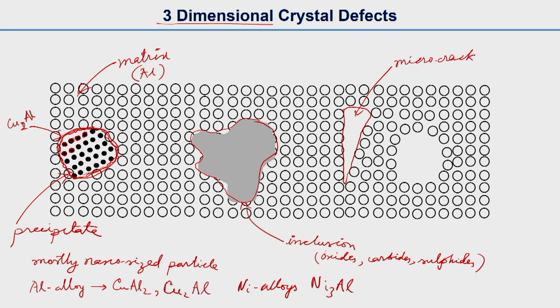These micro cracks generally do not grow very big, you know. In a material there can always exist a good number of micro cracks, but material failure generally does not happen from an individual micro crack. And similarly, there are voids, mostly we call them micro voids. As you know, for ductile material the failure depends on these voids or micro voids.